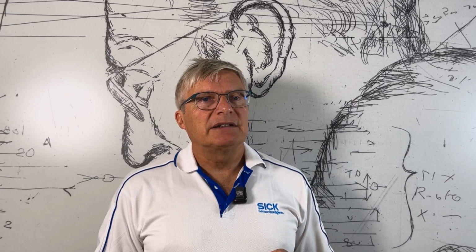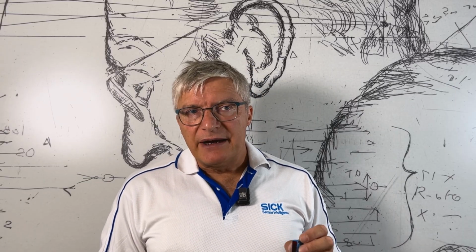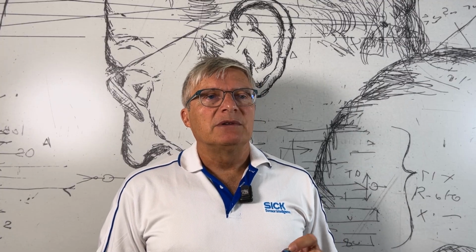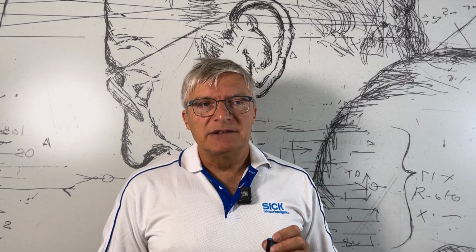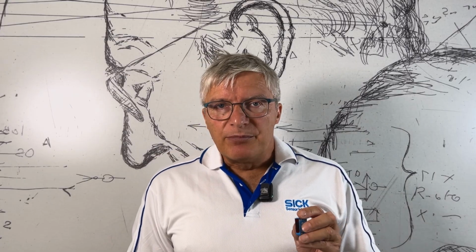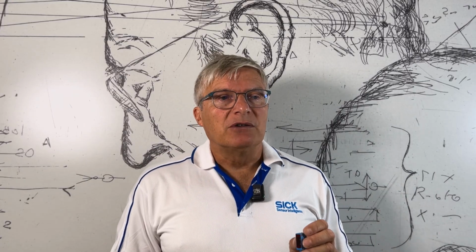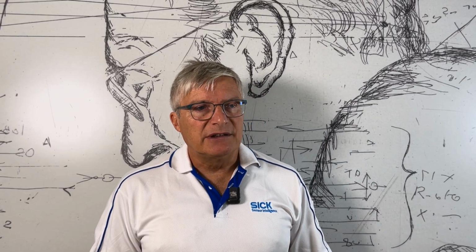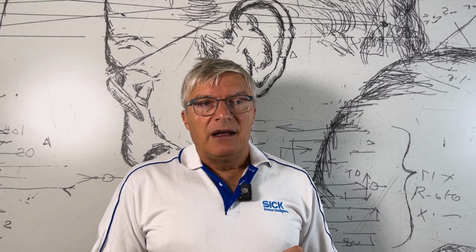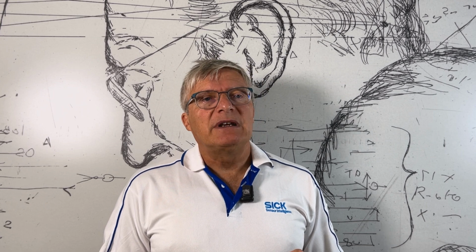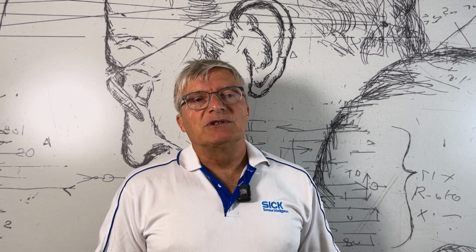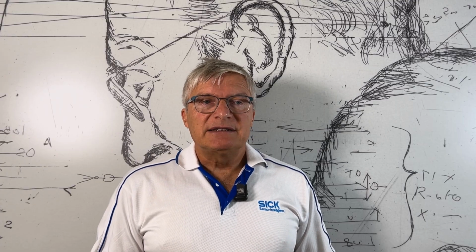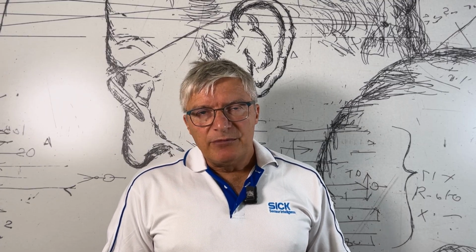Diffuse photoelectric sensors evaluate the reflection of the light from the object or background. The light spot on the object or on the background is projected from the receiver lens onto the receiver. So a precise and unambiguous projection of the light spot on the receiver depends on the quality of the light spot itself. Without halo light, and the sharper and more homogeneous the light spot is, the better is the performance of a diffuse sensor. First, let's look at a classic standard sender LED and its light beam properties.